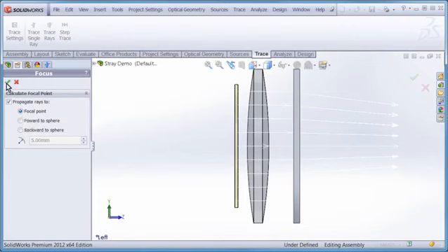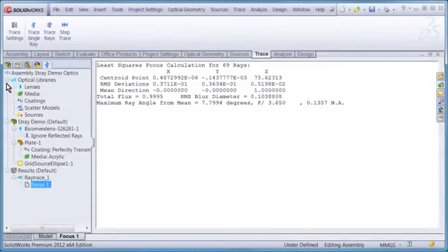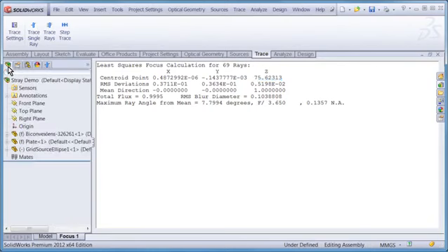So I'll accept that option and click on OK. Now I have the data in front of me. The optimal position is at a z-coordinate of about 75.62. What I'm going to do now is simply copy that piece of information because it will be useful to me in a moment. And we're going to position a detector at that location.